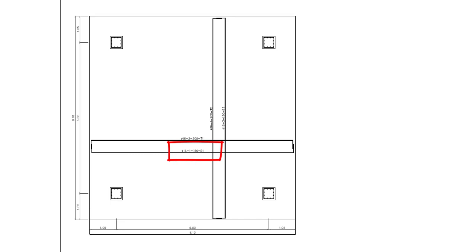16-1-150-B1. 16 means reinforcement with a diameter equal to 16 mm. 1 is the reinforcement mark number. The same mark number is used in the reinforcement schedule table. 150 is the spacing between the reinforcing bars in millimeters. B1 means lower reinforcement in direction 1. T2 means upper reinforcement in direction 2. Direction 1 is the direction of the horizontal axis in the drawing, while direction 2 is the direction of the vertical axis in the drawing.